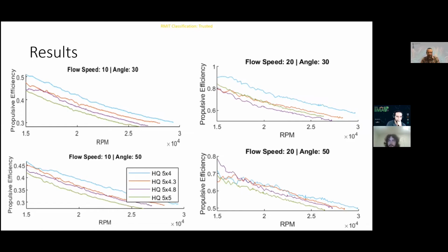And interestingly, with the flight angle, we found that increasing the angle, so getting closer to an axial case, generally gave less efficiency. The angle seemed to have minimal impact from prop to prop. So if we increase the pitch angle of the aircraft, we don't suddenly see a higher pitch prop becoming more efficient than a lower pitch prop.